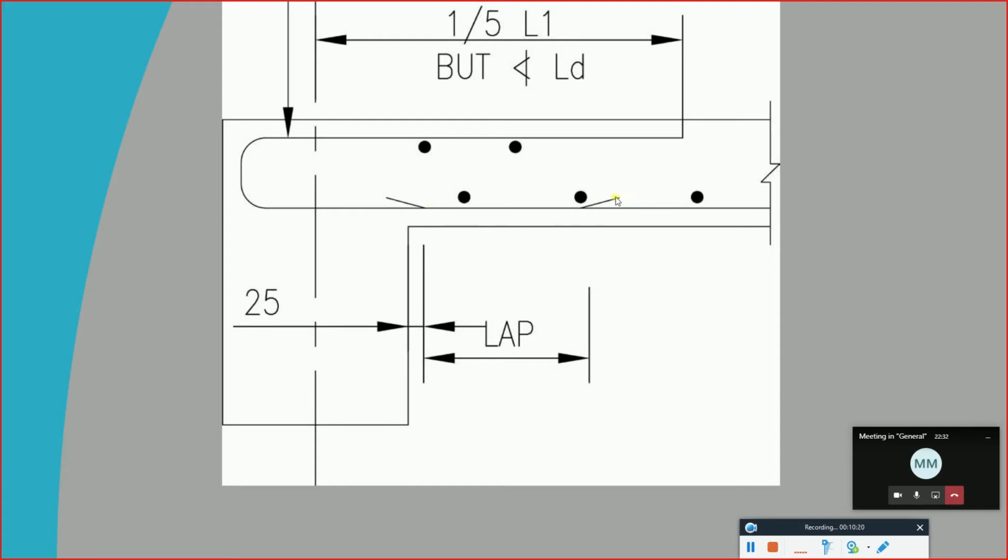And then this is the first part. The second part comes from here. This second part comes for the top bar. It goes from here till the upper side. So if you see now, we have two separate reinforcements. The first reinforcement goes like this. This is going to be the bottom. After that, we are going to have the top starting from here, going for the top portion.